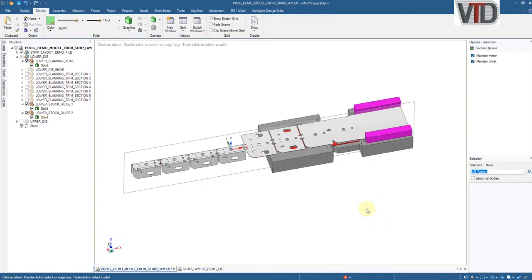That's really important, because when you get to the bill of materials stage of this die, you need to define what each component is as material so that the bill of materials stock list will show that material correctly. By putting these colors on, I'm giving myself a way to filter these components at the end and select them in large groups, and then I can go into the properties and set the material for them at that point.